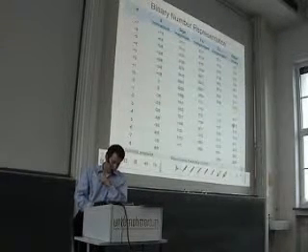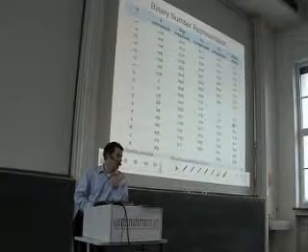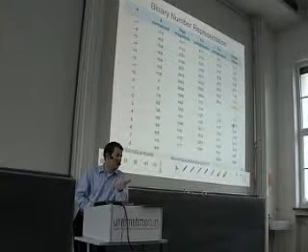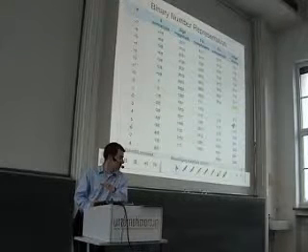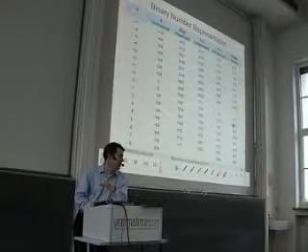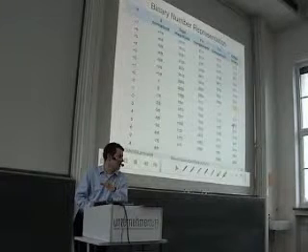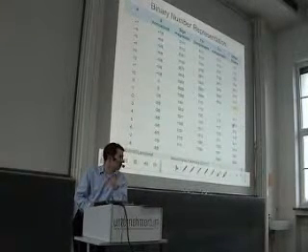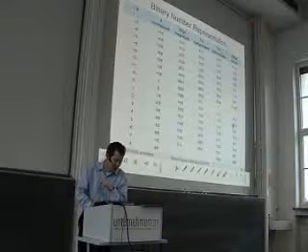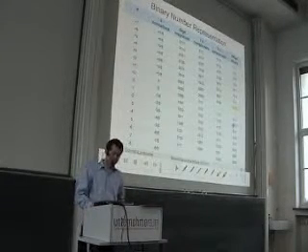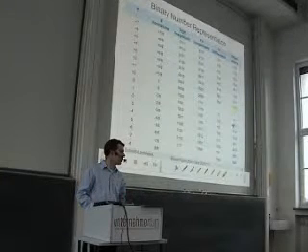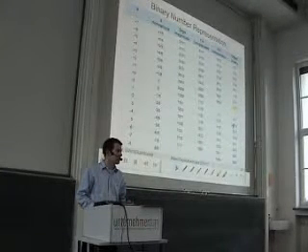So, to summarize, offset binary and sign magnitude are very common in mixed signal, not very common in digital signal processing systems that usually use the 2's complement. So you see there is a need to have some conversion between the number systems when we interface a converter that produces offset binary, for instance, to a digital signal processing system.